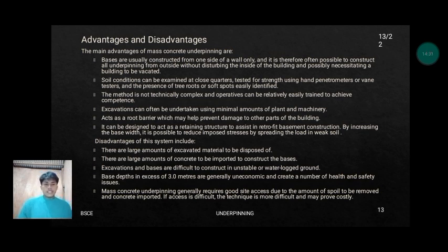Those are the advantages. How about the disadvantages? The disadvantages of this system include that there is a large amount of excavated material to be disposed of. There is a large amount of concrete to be imported to construct the bases. Excavation and bases are difficult to conduct in unstable or waterlogged ground. Base depths in excess of 3 meters are generally uneconomic and create a number of health and safety issues.